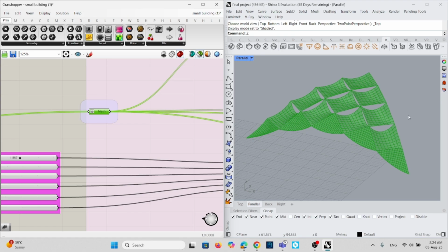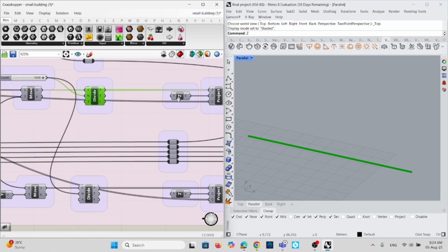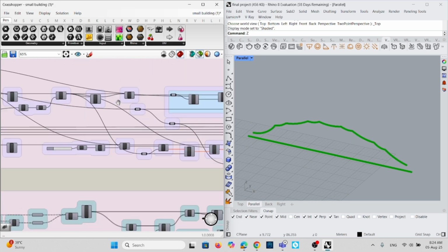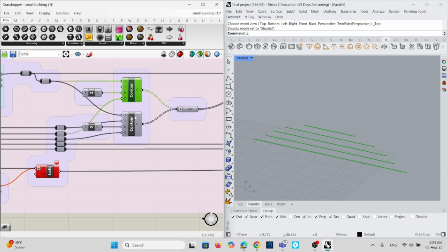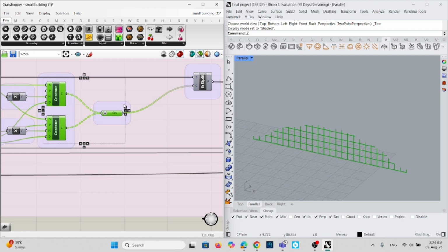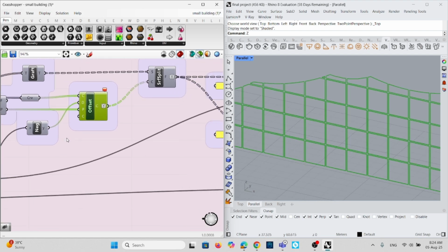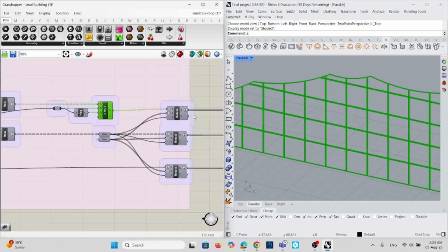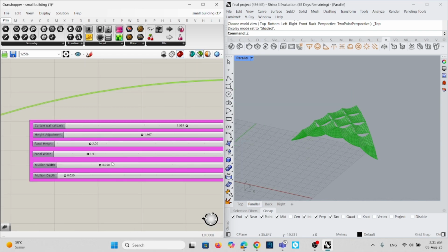After finalizing the roof, I extracted the mesh faces and used their vertices to form the glass geometry. And then vertical and horizontal contour lines were added across the glass surface to form the mullions. These contour lines help us to define the glass segments, which were then offset and extruded to add a thickness for the mullions. And also we can create parametric changes by playing around with those sliders.